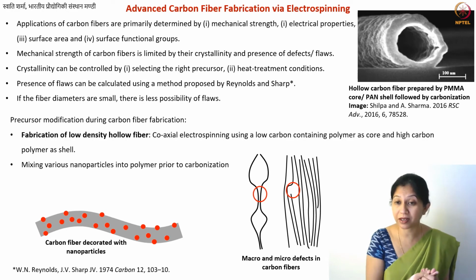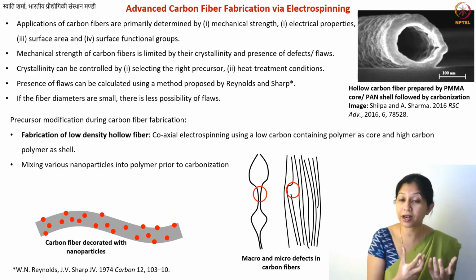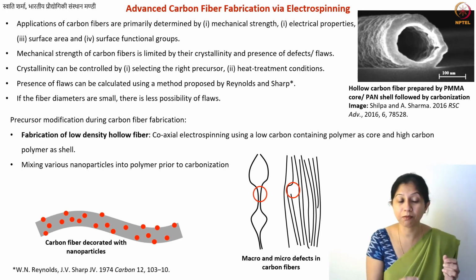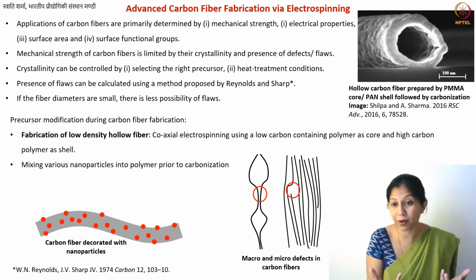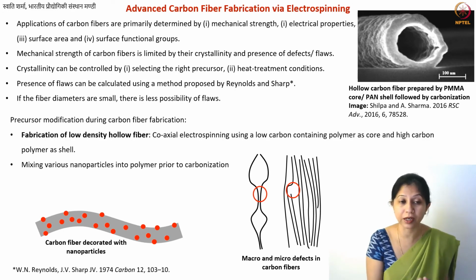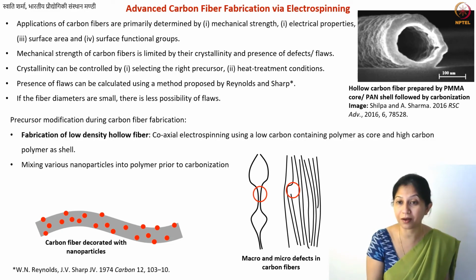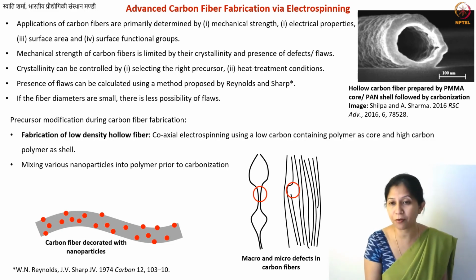Carbon fibers are conductive. If you have a high heat treatment temperature, then you can have conductive carbon fibers. Now you can pass current through these fibers, and you can even perform Joule heating, because if you can pass current through a fiber, then you can heat it by Joule heating. So maybe at a certain temperature, your nanoparticles become activated. Those nanoparticles can then perform sensing of different types, for a number of biological applications.